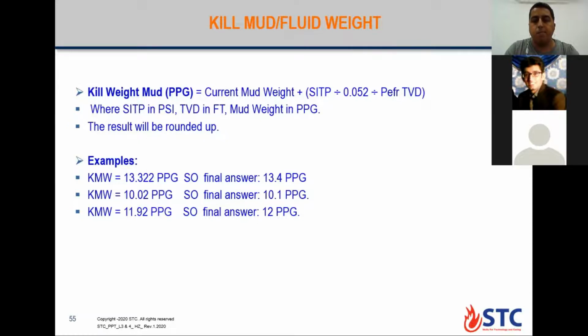But if we are killing the well with the completion, like the tubing, and we have the ability to circulate the well, like we have an open SSD, then should we use reverse circulation or forward circulation? Reverse circulation is the better option, but when would we use forward circulation? Actually, it's up to you. If you need to go with forward circulation, it is your choice. We both end with kill fluid, filling the string and annulus.